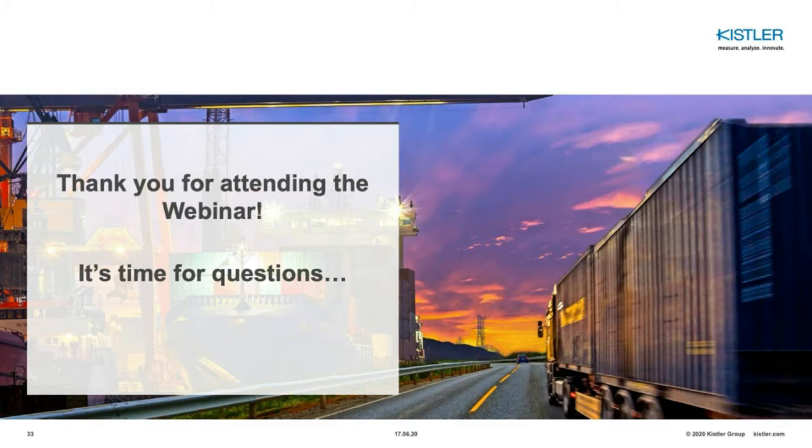If we now take a look, of course, at an installed sensor in the road, normally the sensors are replaced after between 5 to 10 years if you do some maintenance on the road and make sure that the sensors are, for example, well flush grinded with the road. They really get these long lifetimes, and here we expect the same lifetimes for the Lineas digital sensors, these new ones, like we have for the existing Lineas sensors, which you know since more than 20 years. So from our point of view, it's mainly the road that is the limiting factor in the lifetime of a WIM sensor.